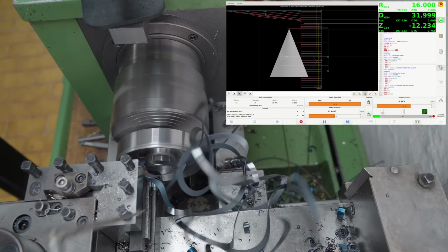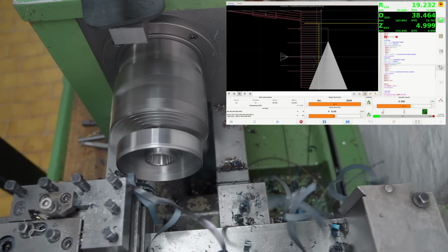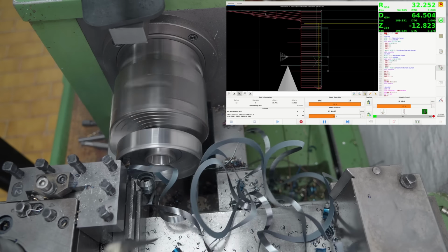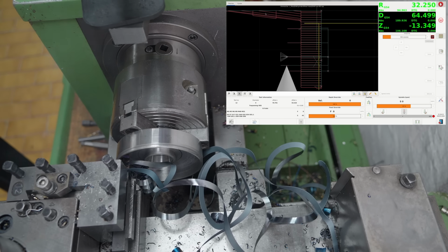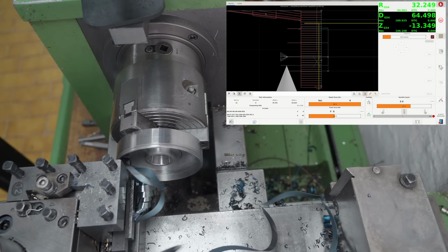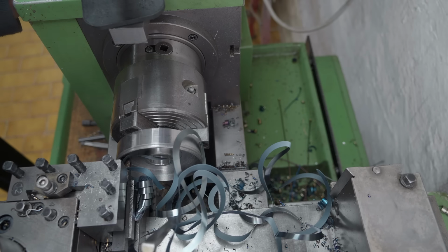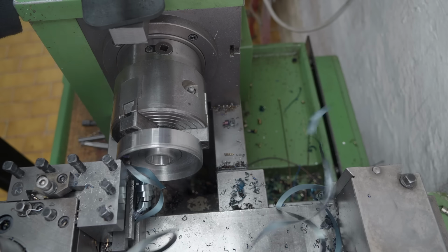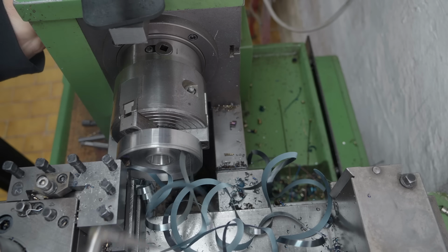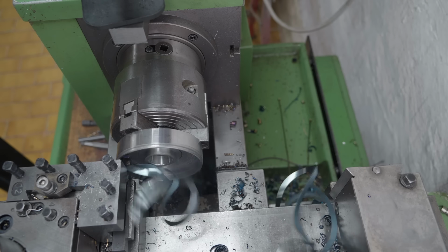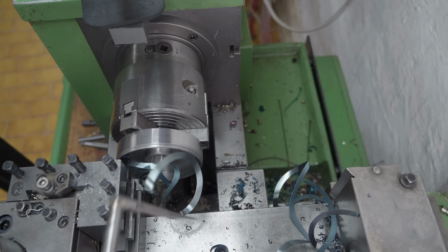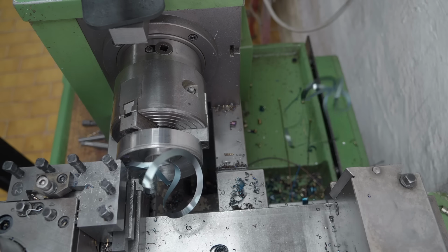Now the transition from trepanning at this smaller diameter out to do the balance weight dovetail clean out, the spindle speed didn't adjust fast enough and I stalled out. I guess what happened there is I didn't give it time for its speed change, so it needs time to slow back down. This is about where I gave up on ChatGPT and switched over to Claude AI to help me program it. And that was a big step backwards.